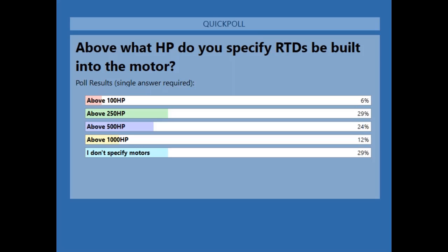So typically what we see, because we have 12 RTDs available, we have 6 in the stator, 2 on the motor bearings, 2 on the pump bearings. Then we have 1 on a pump case if you've got a pump case. And the last one we use for ambient. One thing is we can use on both 369, 469, and 869, that ambient can be used in the thermal model.